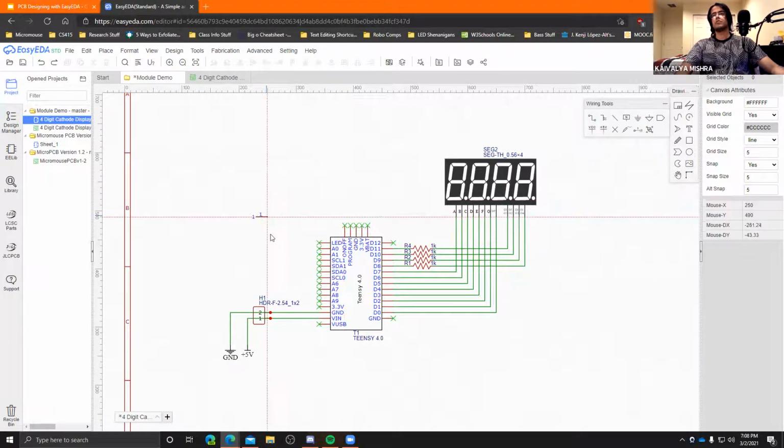Okay. And then there's a pin tool, which you can use if you want to set up certain connections on the board that are not related to any component, just your own personal pins that you want to attach, either to another board or something, with some wiring or cabling. You have the pin tool, which you can also assign nets to and then connect to other pins. We're not going to be really using that. I'm just showing you that it is a tool that you can use.